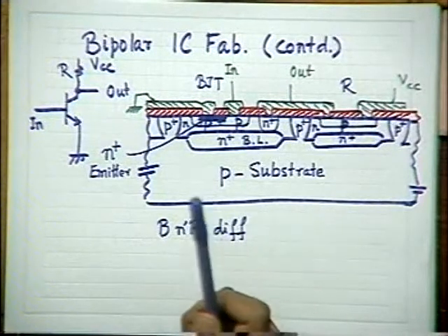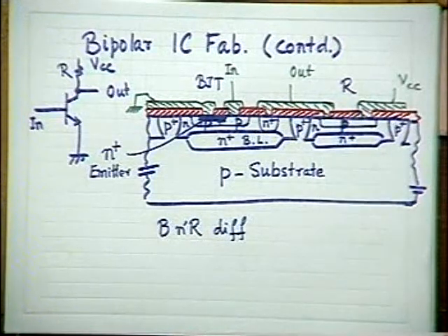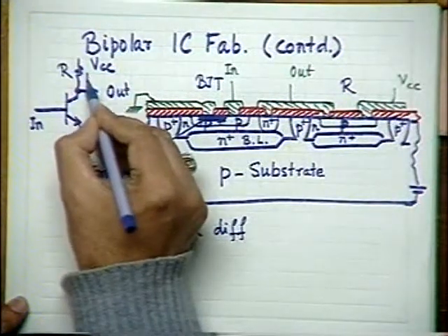Whereas in bipolar, you have to have a constant gain, and it's direct coupled in many applications. And unless we maintain the biasing conditions properly, it will not work satisfactorily. That's the difference. A bipolar integrated circuit, a linear integrated circuit, is therefore design-wise more complicated than a digital integrated circuit. Please remember this.